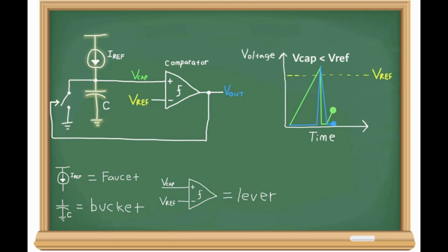So, components like the reference current and the comparator need to be designed very carefully to ensure that they operate as expected and don't degrade the stability of the oscillator. Even after dozens of years, circuit design engineers are still coming up with new ways to design oscillators, so that they have higher stability or they're more power efficient.